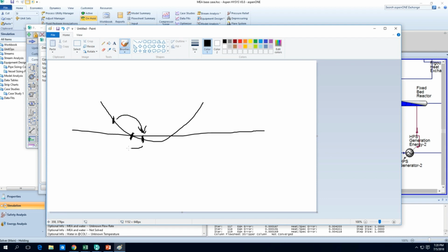But what you see here is probably a minimum step size. So at the second instance, maybe HYSYS will be jumping here. So it's missed the solution again. So HYSYS will try to re-guess, and maybe you'll end up somewhere here. So the effect is that you keep oscillating back and forth because the step size is too big.